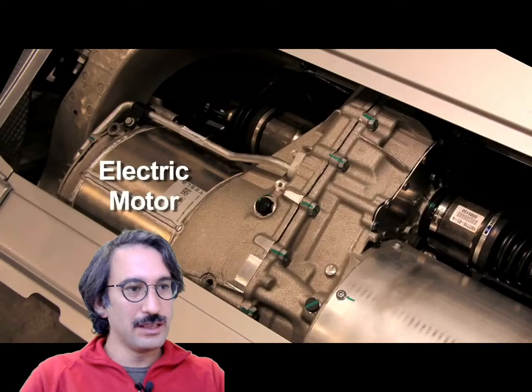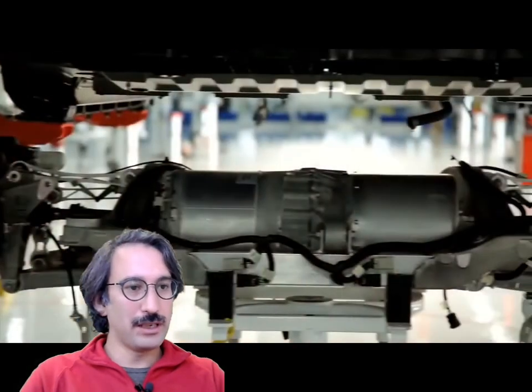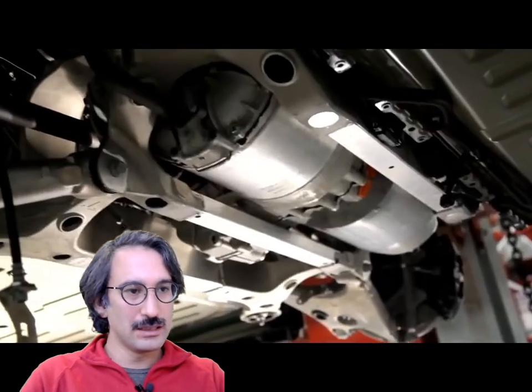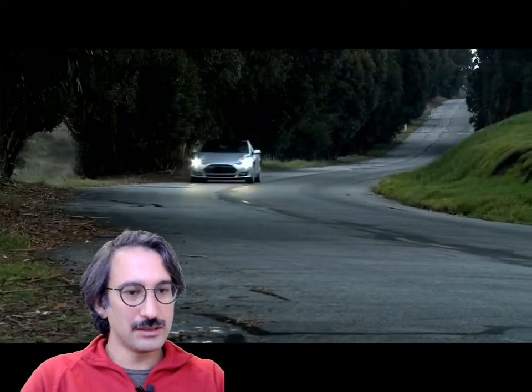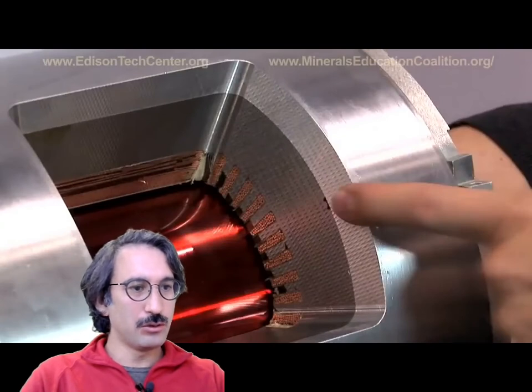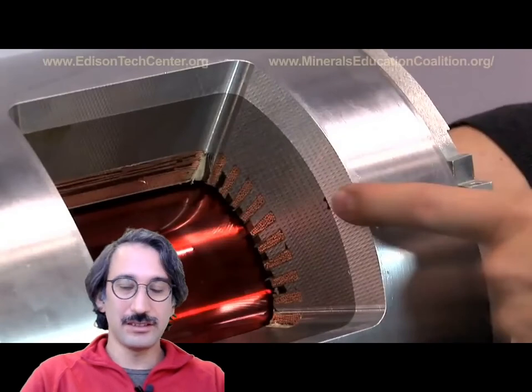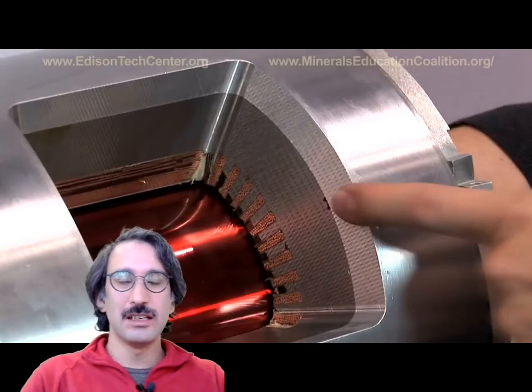So you have the electric motor on the rear wheel, and next to that you have the power electronics. They are connected together, and you can control it. Let's have a look at what is inside the motor. It consists of two parts: the rotor, the aluminum rotor, and the stator. Again, this is not a DC machine. This is an AC machine.